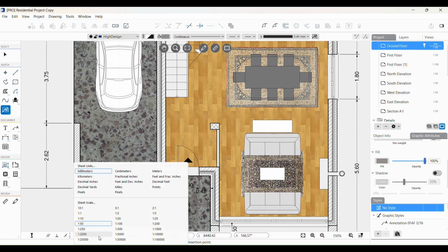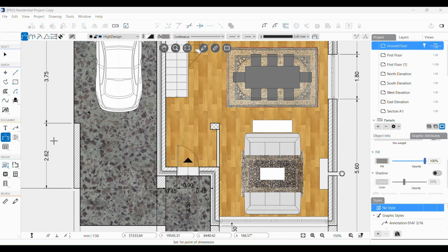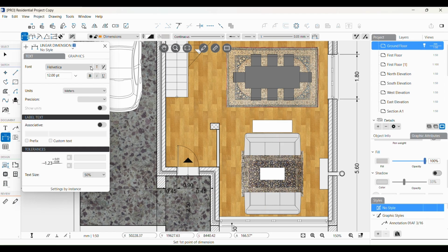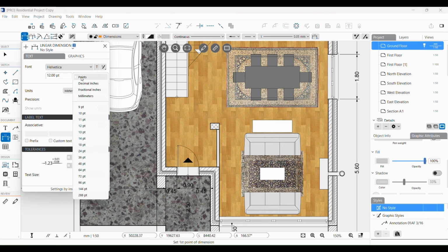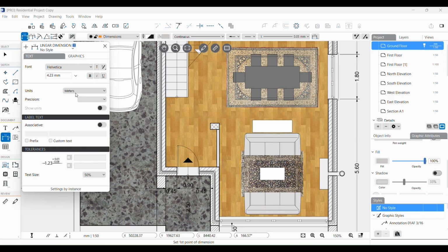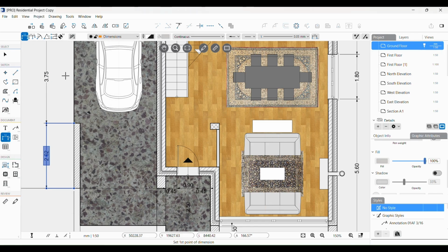Each sheet in a project can have its own drawing scale. Measures and dimensions must be entered in their natural, real-world scale and are automatically adjusted to the current scale. Annotative objects, like texts, annotations, and dimensions are entered at their 1:1 scale. You can also draw at real scale 1:1, as in other CAD apps.